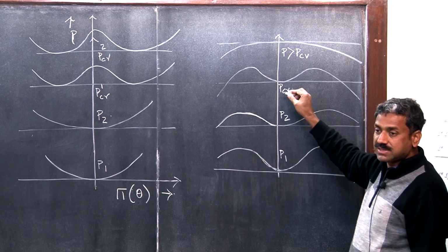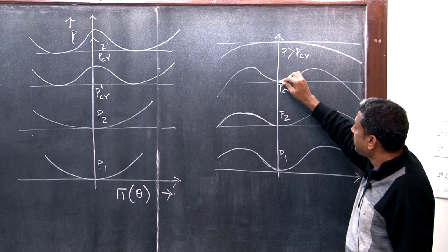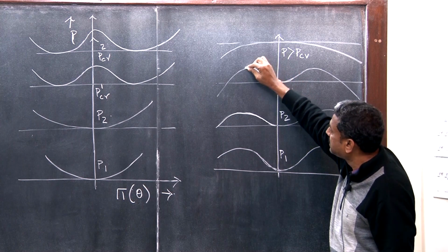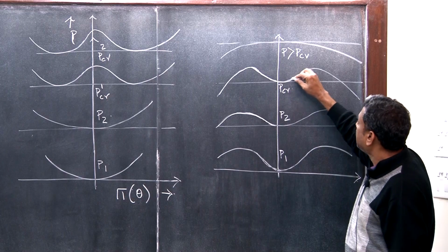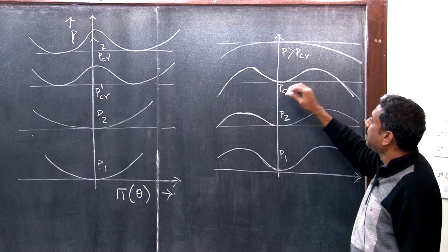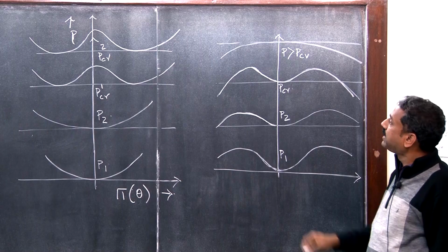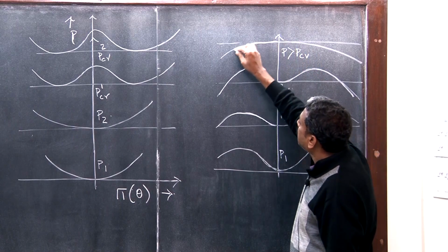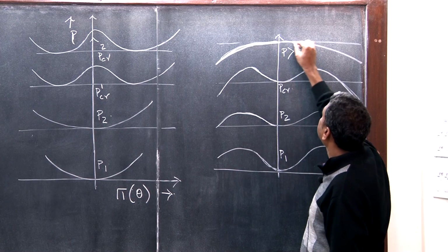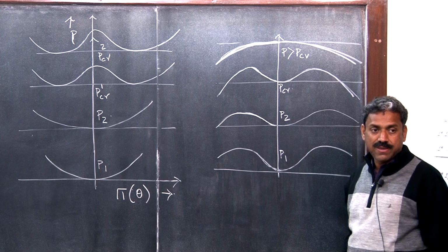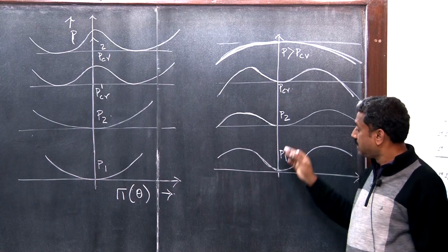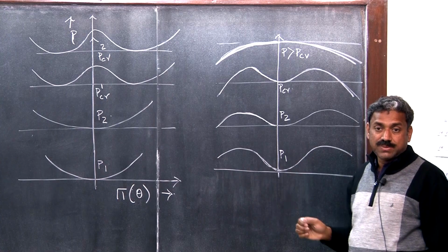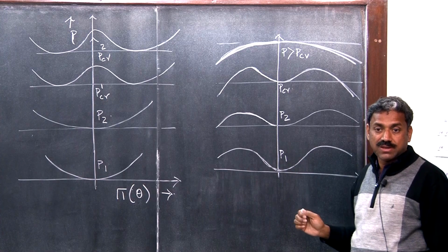As soon as it reaches the critical value, this becomes unstable, but here it still remains like this, okay. But as it is much higher than critical, you see what happened. You see that these are unstable. You see that this becomes convex, okay. That means the post critical path is unstable. Understand? This is for the symmetric but unstable post critical behavior, right?